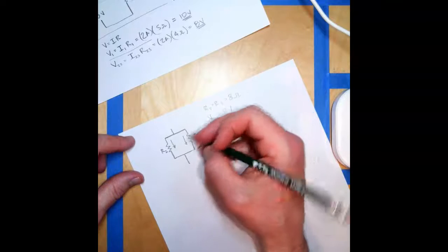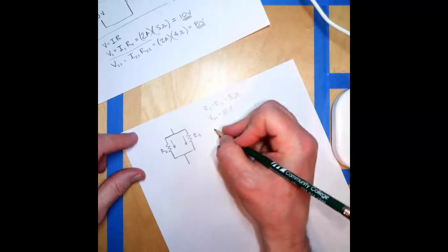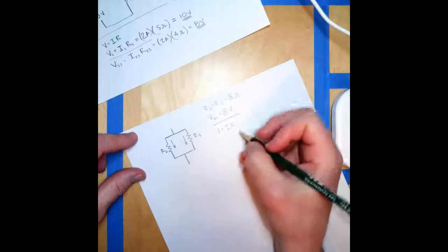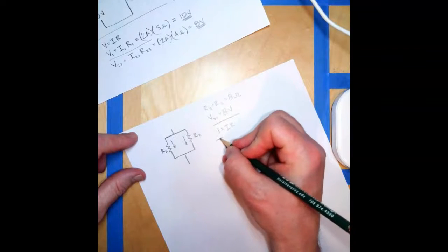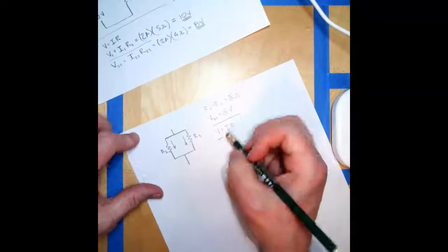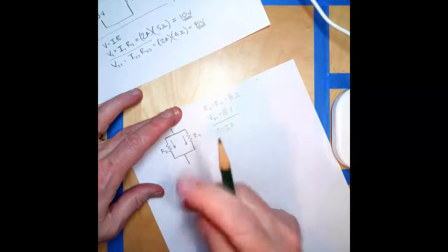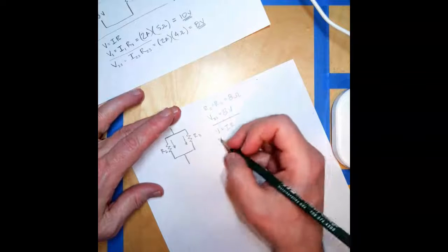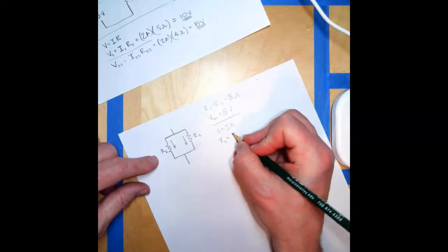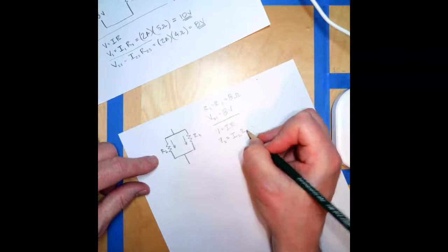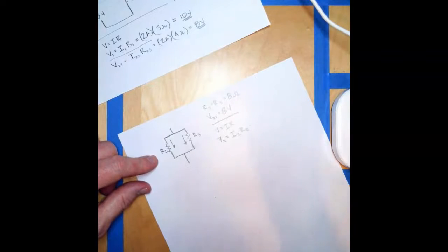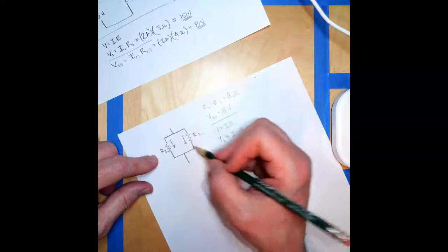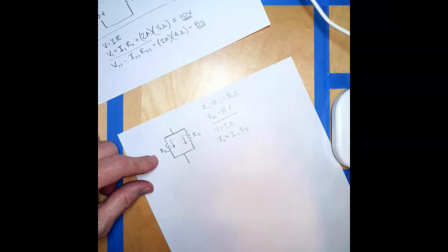Now we can calculate how the current changes. We know that V equals IR. So let's do voltage 2 is equal to I2 R2. What is voltage 2? Again, it's the same as voltage 23. It's 8 volts, so we have 8 volts coming across here.